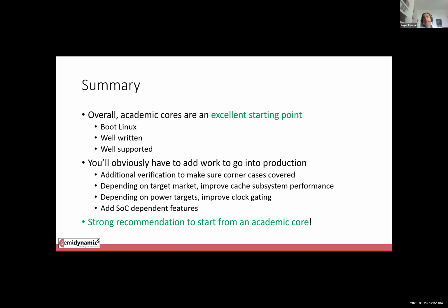No, I mean, my experience was that we started with Chisel. We trained 4 designers to write in Chisel. They did write some code in Chisel. And our experience is that there is a lack of support for something like, if you know Synopsys Verdi, their equivalent from Cadence and from Mentor, if you've worked on these tools, you know that when you're debugging in your waveform, you can double click on any variable in your Verilog, and it will take you to the waveform and take you to the source code.